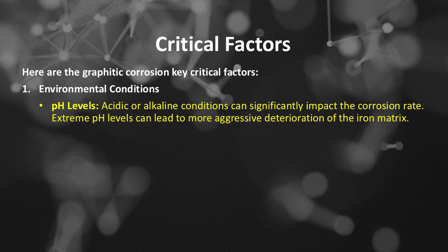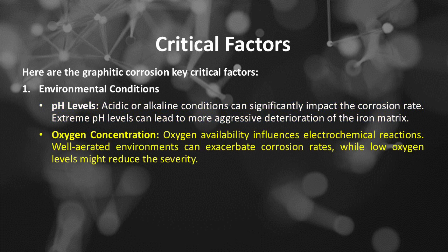pH levels. Acidic or alkaline conditions can significantly impact the corrosion rate. Extreme pH levels can lead to more aggressive deterioration of the iron matrix. Oxygen concentration. Oxygen availability influences electrochemical reactions. Well-aerated environments can exacerbate corrosion rates, while low oxygen levels might reduce the severity.